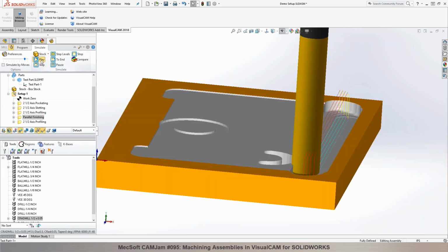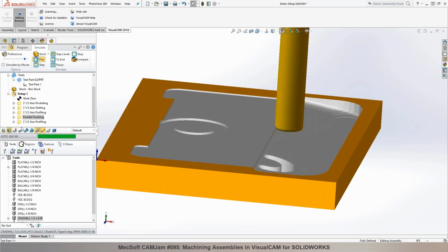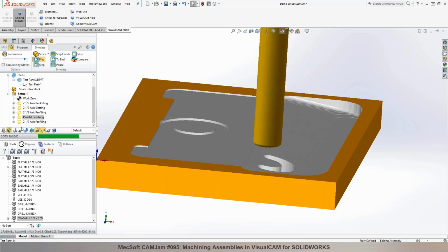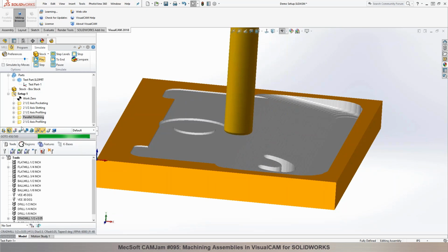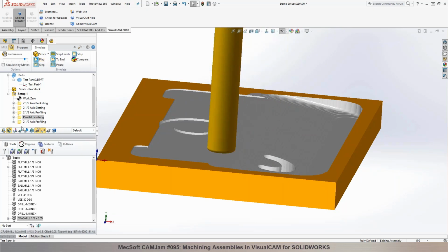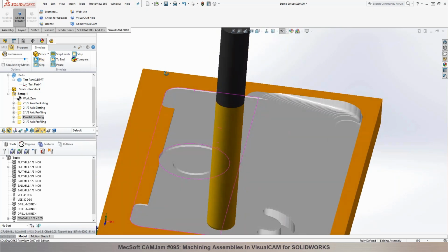So you can see this is a corner radius tool. If I switch it to a ball mill, you're going to get an even much finer finish. Okay, yeah, cool. And also the direction in which you're cutting, you can determine that. Yeah. Okay?